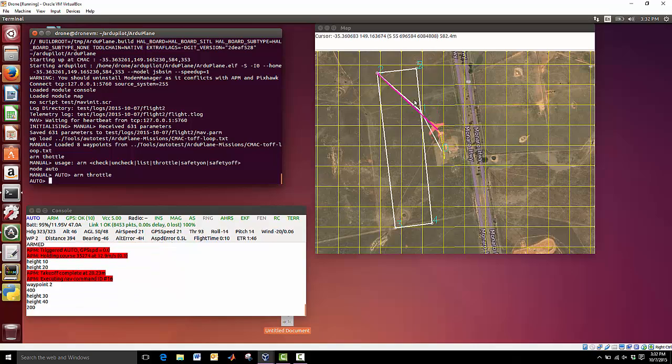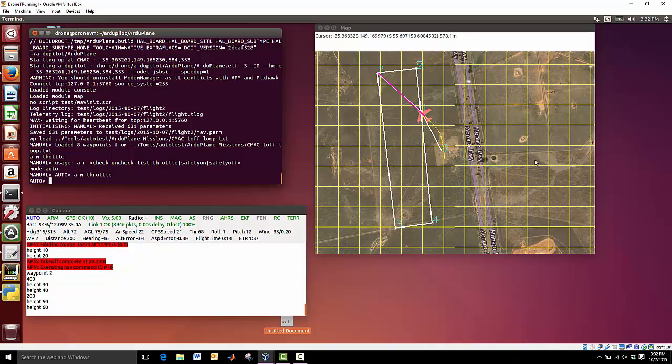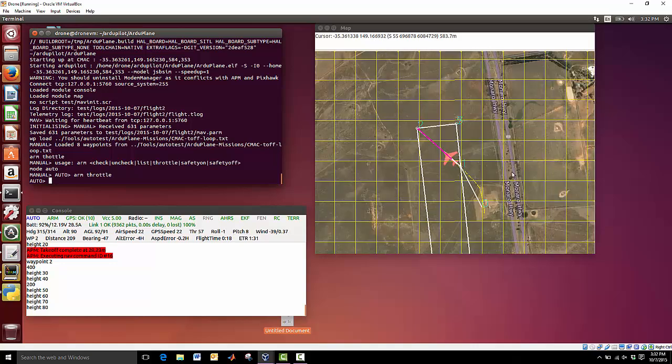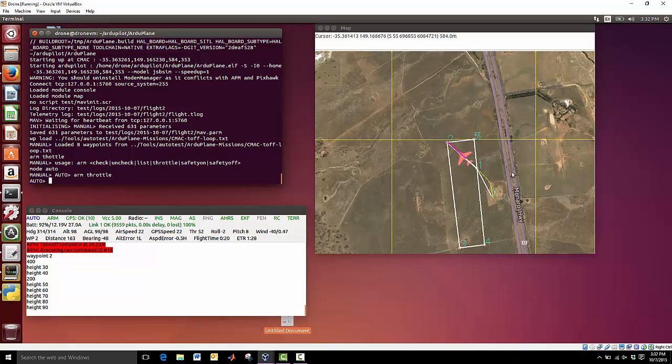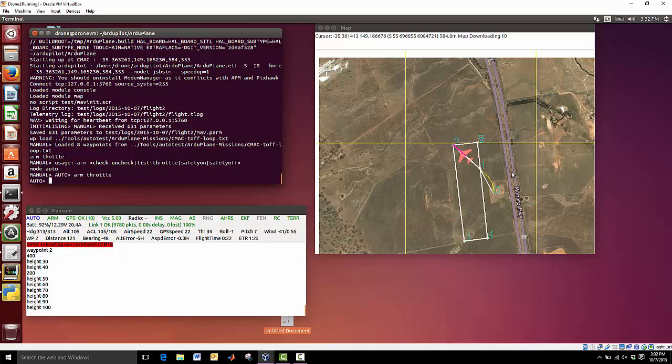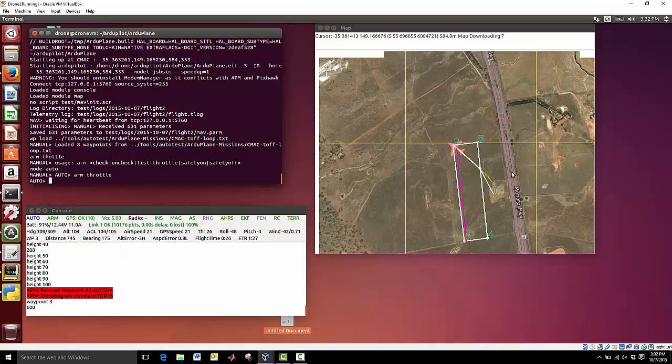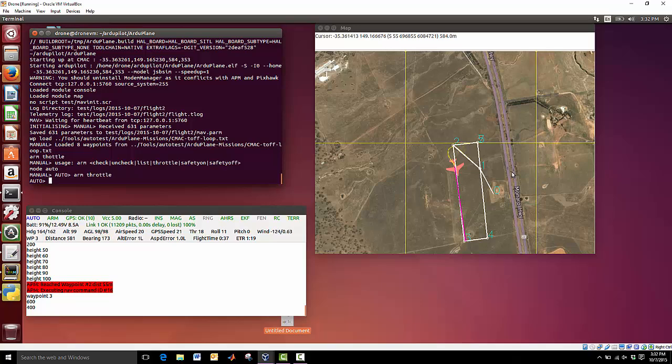Okay, so we started up. The drone's going to follow this pre-planned track that I've laid out for it. So it takes off. It's going to get to an altitude of 100 feet, which you can see the altitude climbing right now. And then it's going to follow this kind of box pattern around the airport. This is the auto mode of flight, where it's following pre-established waypoints.